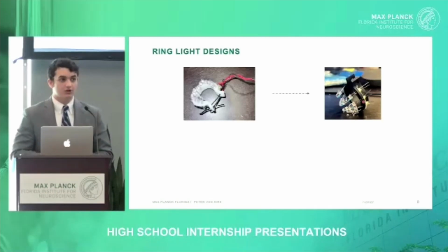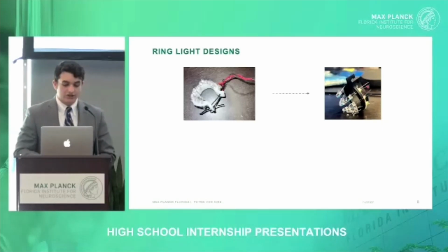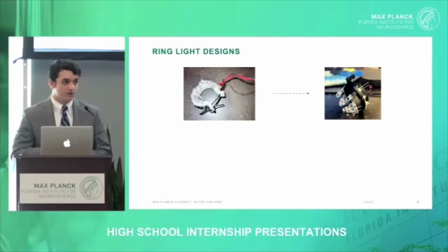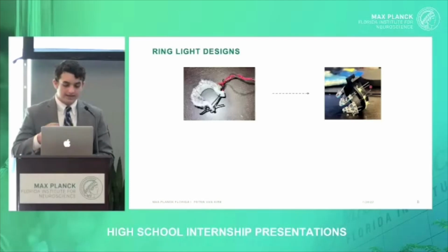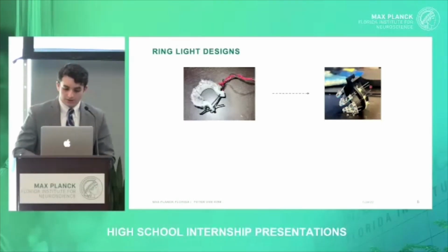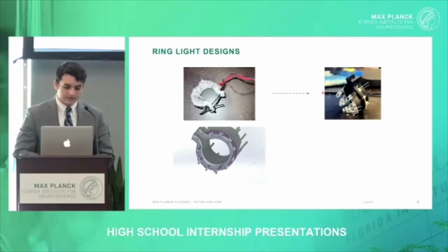However, there were some additional problems that were introduced here. The prongs were too close together. If you have any experience with soldering, it's very difficult to solder these parts together because if you cross the positive and the negative, you could short the bulb and then you can't use the bulb, or you could even attach the red and green LEDs on the same wire, which is not what we're trying to do. We need to have the red on a separate one and the green on a separate one so we can test them separately. So I created a third design.